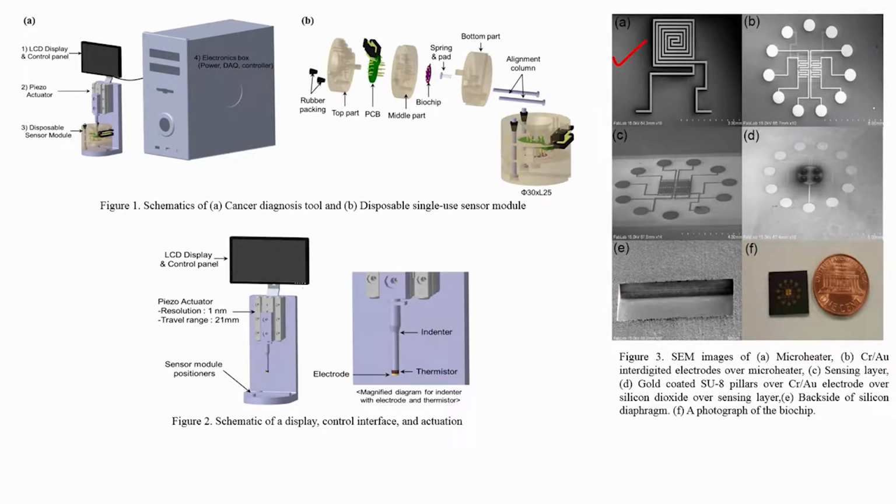After the heater you have an insulating material. On the insulating material you can have interdigitated electrodes. Once you have interdigitated electrodes, again you know how to fabricate them. You deposit metal and use lithography technique to form interdigitated electrodes. On these interdigitated electrodes you can deposit the sensing material, and this sensing material is your piezoresistive material.